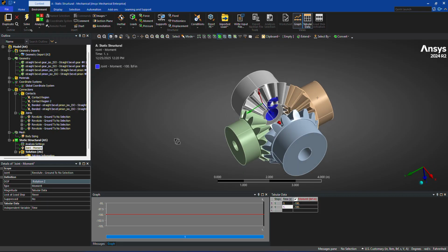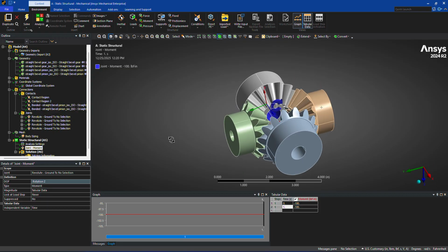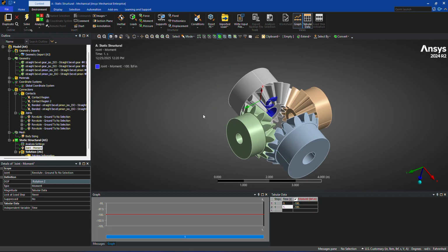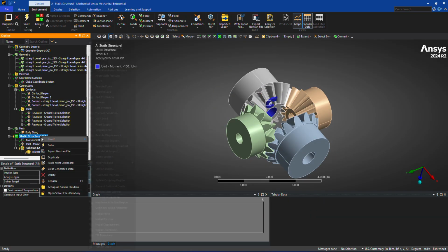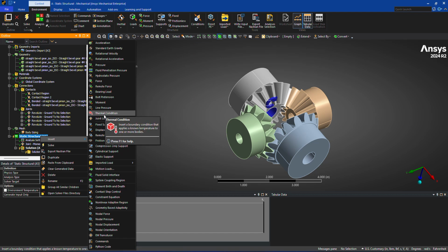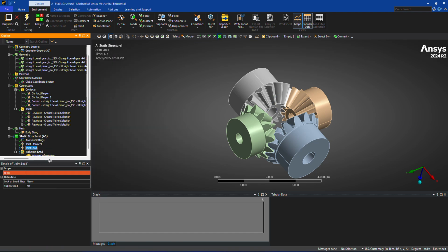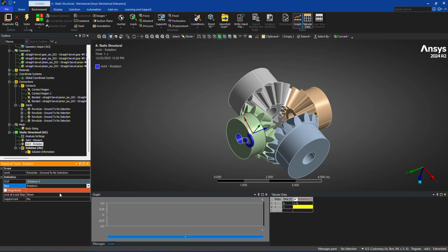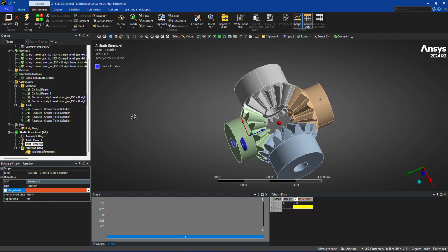All right, so I guess it's okay. In this direction it will rotate anyhow. And for the rest of the parts, also select joint load, but this time select this one, give the type as just rotation, and you will give just the angular value, that's it.